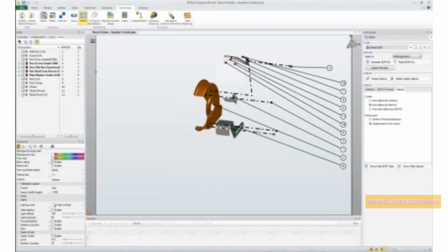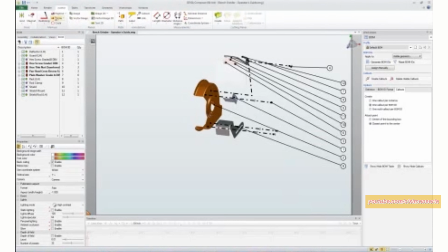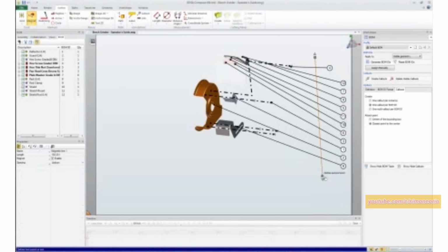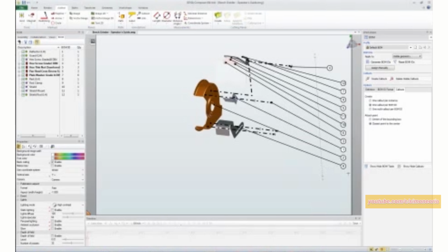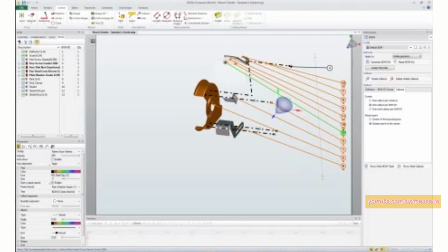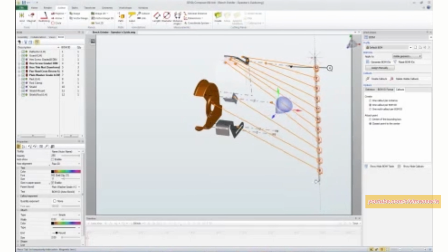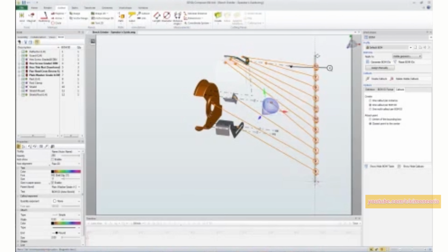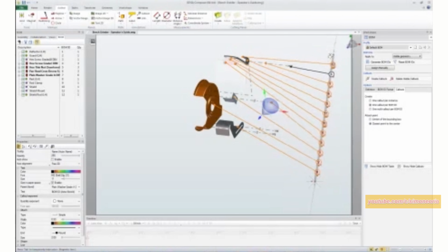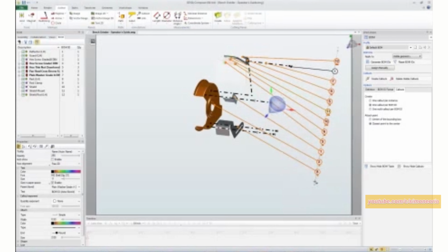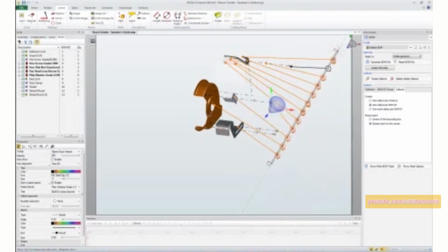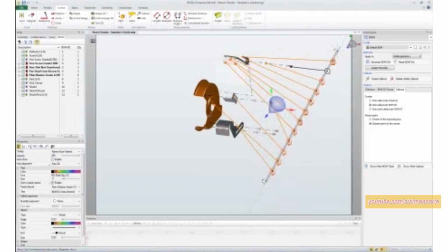However, we have another tool available called the magnet line, and what's nice about this is you can actually define the magnet line and you can select which balloons you would like to be attached to the magnet line. Just click those and drag them and see they all attached to the magnet line all at once. And the other nice thing is if I happen to drag the magnet line across and pick up that last one, there we go. So now I can adjust and align all of my balloons along the model.